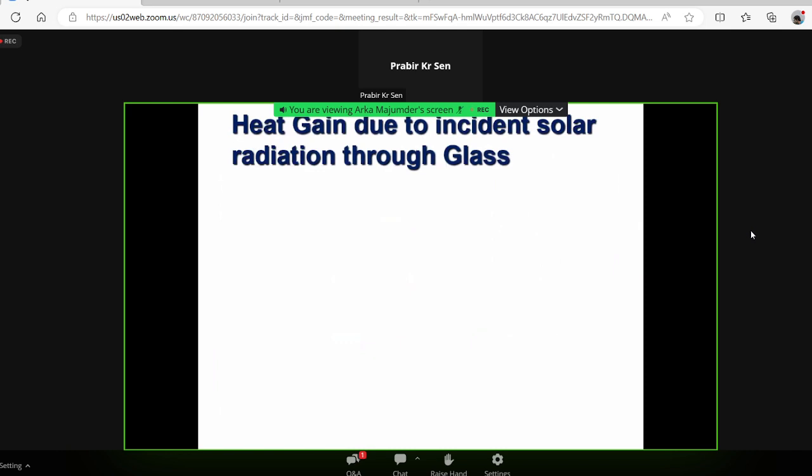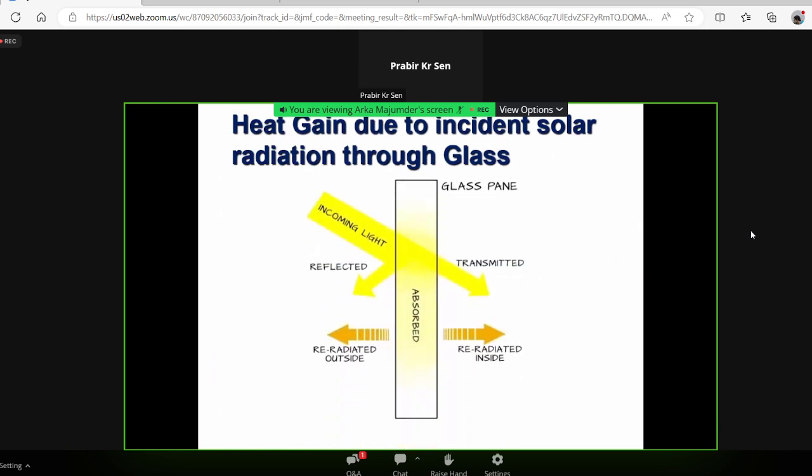Glass and windows I have said. Next. The part of the light falling on the outside surface gets reflected, but part comes directly inside, which doesn't come directly inside for walls or roofs. Other phenomena are the same. The glass will get heated up, radiate heat inside, outside, all these things are the same. So direct transmission is a very big part, so we have to take it. Next.